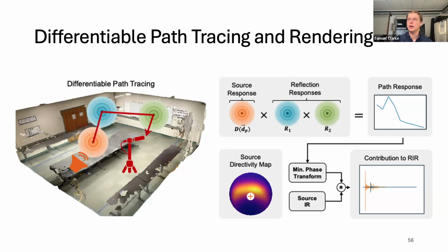We didn't find too many measurements out there which backed up the efficacy of that model for modeling reflections. So we would have to look at a finer granularity of the time domain, or maybe even the frequency domain, especially the phase, to the extent that the phase is not too influenced by noise, in order to determine whether we could have modeled the reflection better than with the minimum phase frequency filter.